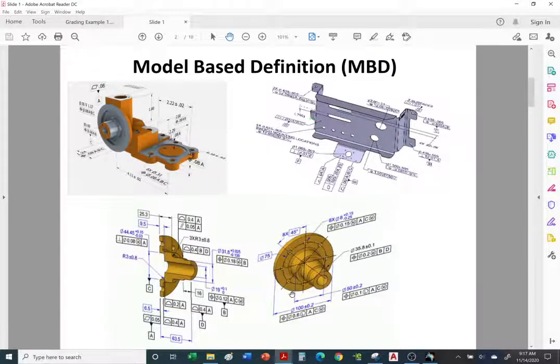Here's something that we have in metric, millimeters. Most of your dimensions will be either in inches or millimeters. Okay, so once again, you open up the model. And if you don't have a dimension, if you want to know a dimension, for example, maybe the height of this shaft, or maybe the thickness of this flange, you'd measure it directly from the model and apply whatever tolerance is included in the statement of work and the documentation.